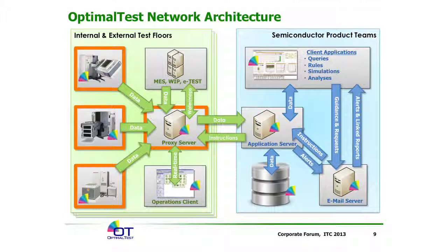So all of the data collected by these testers, by OT-Proxy components, are sent to the proxy server component, which is a server or set of servers installed at the test house itself. Those servers collect all of the data. They can also augment that data with additional information from MES systems. So for example, very often data logs don't contain product identifiers or other pieces of information that's useful. We can pull that information from the MES system. We can also pull information from MES such as quantity in, quantity out, and so on.